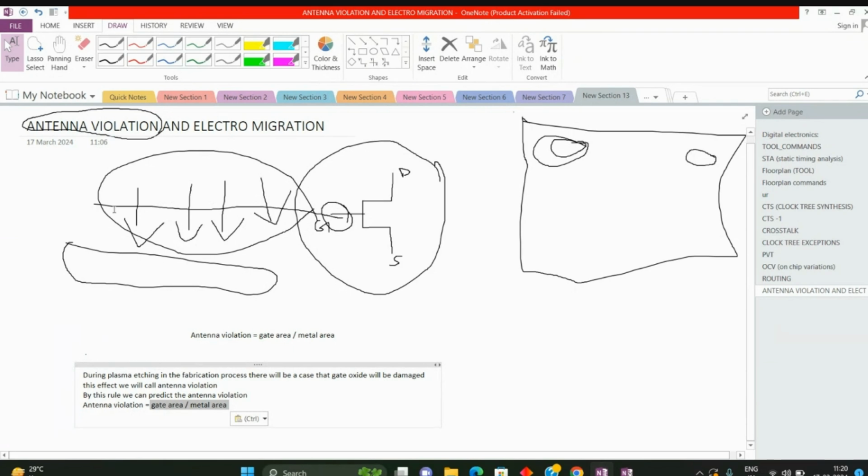If the net length is very long, as I told you many times, when you come to the ECO stages, every violation you can fix either by sizing the cell, or by seeing how long the net is and breaking the net. Many violations will be resolved by these two methods only. You don't need to use any clock balancing techniques or placement blockages.